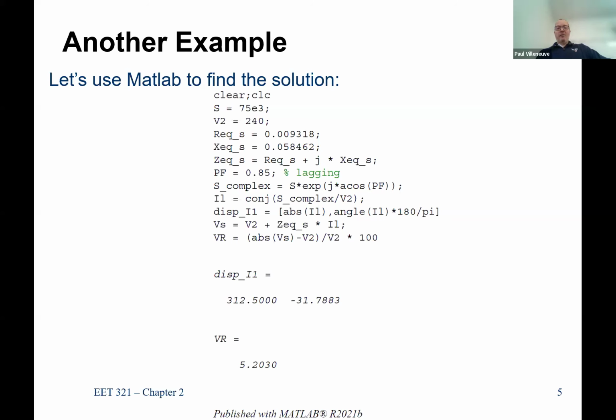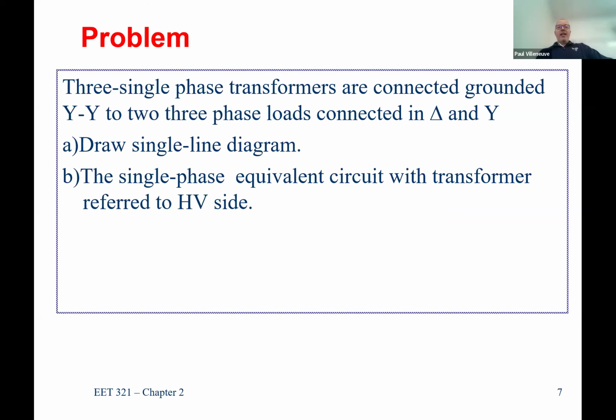So what it's worth. All right, let's go ahead and connect some transformers. And why do we need to connect transformers? Because there's no such thing as a three-phase transformer. Say, what? Well, we call it three-phase transformer, but it really is single-phase transformers connected in such a manner to provide a three-phase load and source.